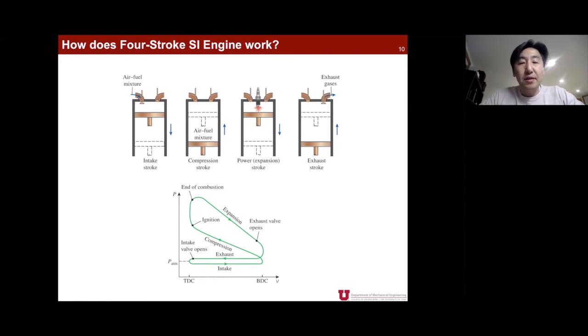Now you have high pressure air and fuel mixture that is already at quite high temperature, and they are ready to burn, but they don't have high enough pressure and temperature to ignite themselves. But at that moment, the spark plug helps them, like, okay, now let's ignite. Then in a very short time frame, your air and fuel mixture has a drastic chemical reaction, a combustion process that totally burns up everything. It happens so quickly.